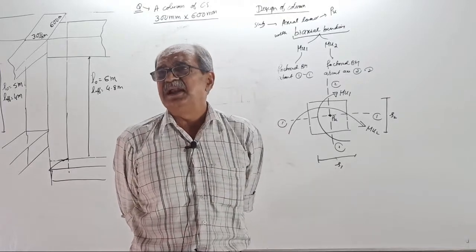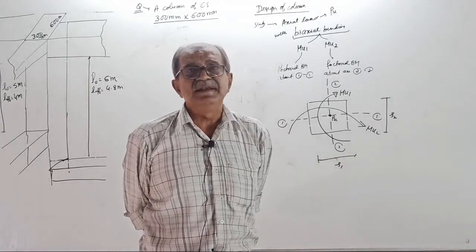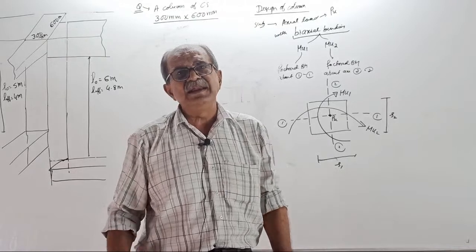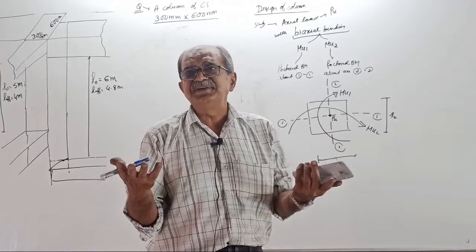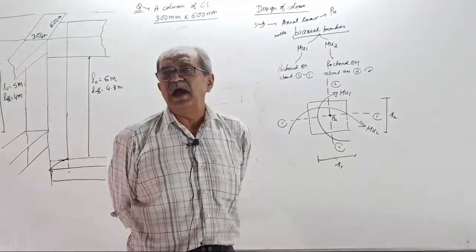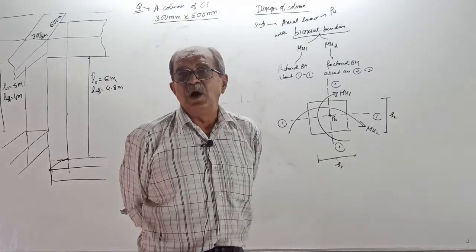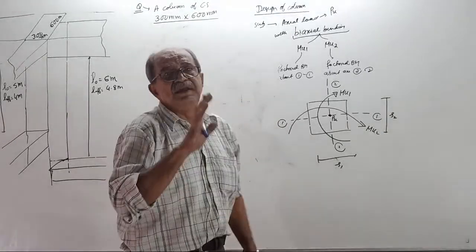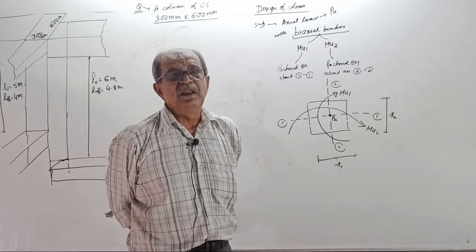Therefore, in SP16 the interaction diagram is not there. ETABS is not bothered because ETABS is not using SP16. ETABS is using the equation. So for ETABS, there is no problem. Why? It uses the equation. But practically what to do? Actually, long back, when I started the course around 10 years earlier, in one of the first professional training batches, I derived interaction diagrams for them. How interaction diagrams are prepared, what is the principle, etc.